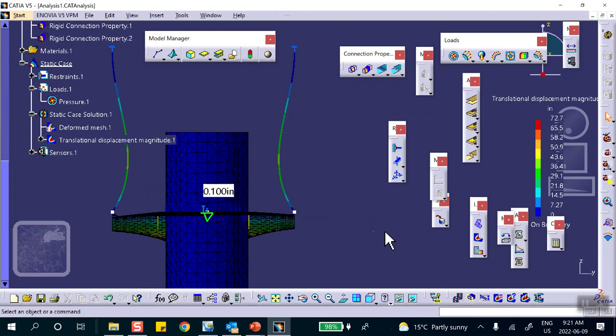Now, why did these beams actually bend like that? Imagine you bought this thing from Canadian Tire, put it together, welded this thing to that thing, welded the edge of the beam to this somehow, and then loaded it. Will that come directly down? Well, if instead of a weld you put a hook there, this becomes actually a cable, not a beam. Right now, because we made it rigid, and that point on the shell is rotating, it takes the beam with it. Whatever the shell does, this also does, bends.